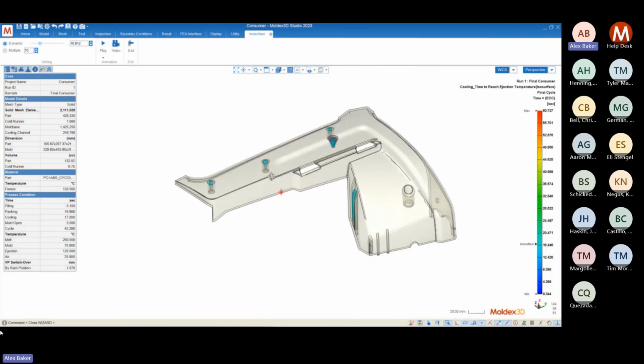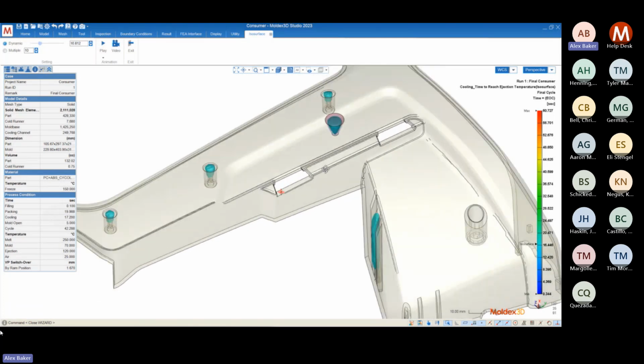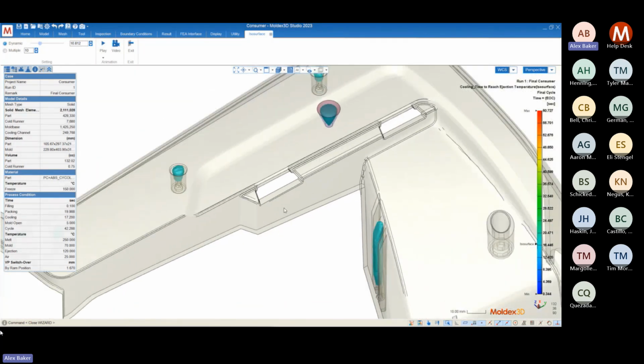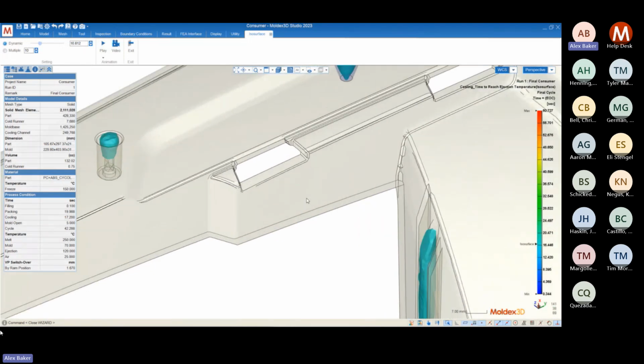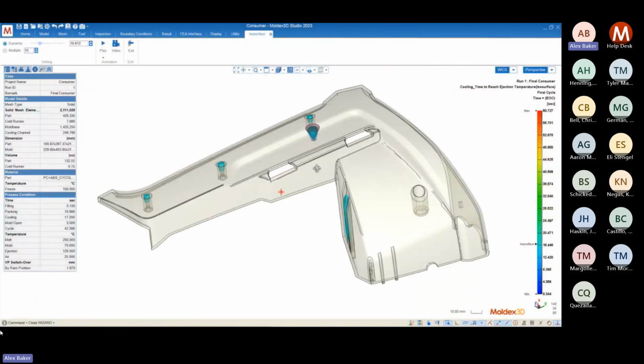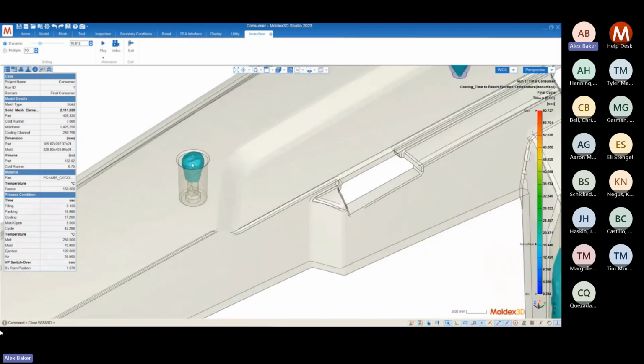But even from there, if I'm looking at the simulation results, I will know where I can strategically place my ejector pins so that I don't have to interact with these hotter surfaces. In this case, we saw from the thickness distribution that this surface is about 0.5 millimeter thicker than the rest of the part. If that's the case, then we can just avoid putting ejector pins near this surface. In that case, this surface almost is similar to these bosses.